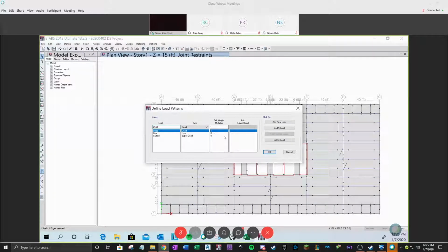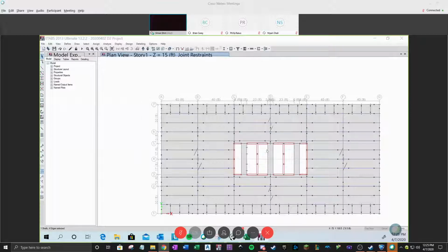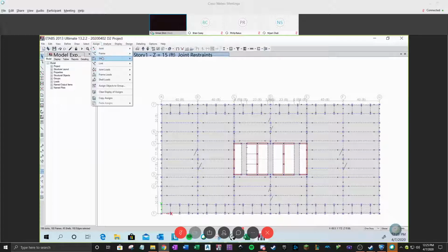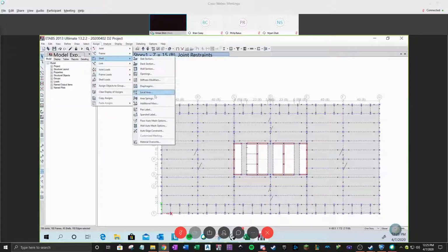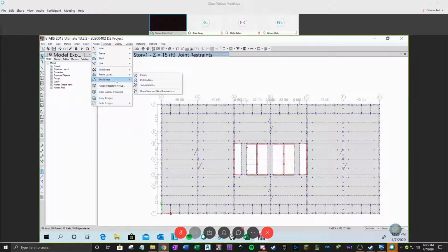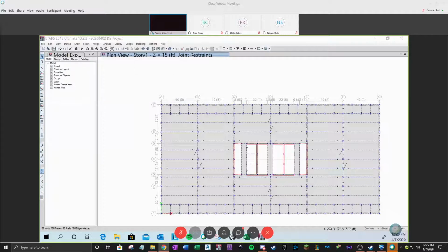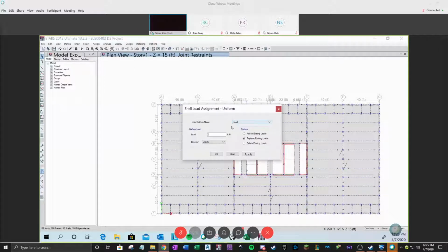And all the side structures. So we'd like to keep it one. And I'm going to choose, for now, to delete those 46 PSF, because otherwise we doubled the self slab weight. So that load, I'm going to put the 0.